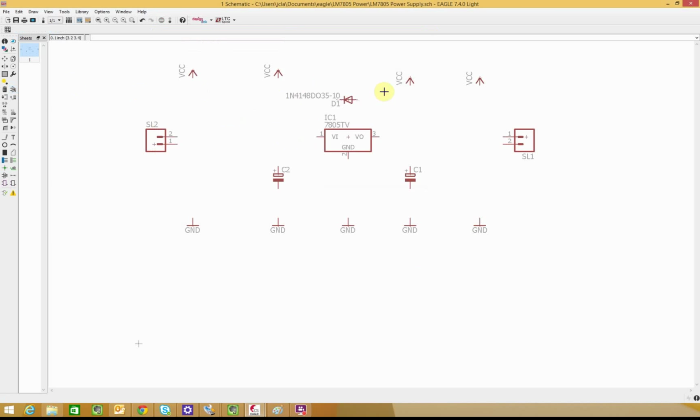So these two I need to move up a little bit, so I'll take hold of my move tool over here and just move them up one step like this. So now we need to connect everything here. And we go over here and grab the wire tool and then click and connect them. And in order to release the wire, you just press escape and ground up here.